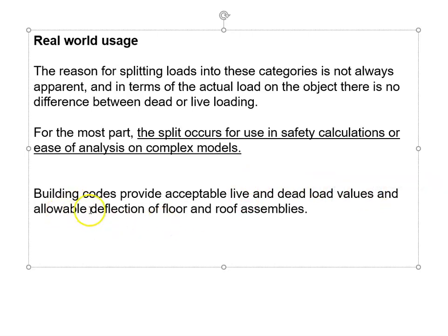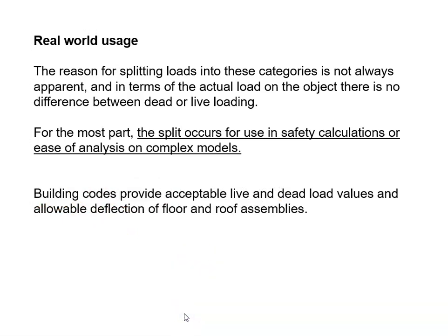And it tells you that your floor is allowed to deflect or bounce a little bit. All right, so in some situations, a little bit of movement's okay. And I talk about my old house quite a bit. So when I walk across my living room, there's a little deflection in the floor, and that's normal. It's an elastic load. It's there when I'm walking on it, but then when I get off, the floor bounces back and it's fine. And the building code will tell the engineers exactly how much little bit of bounce you're allowed to have. Okay? So that's how codes play part of that role.